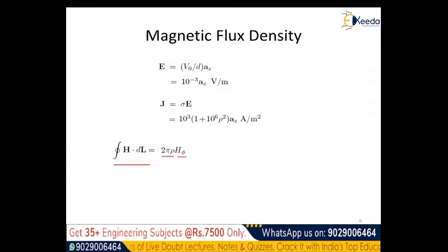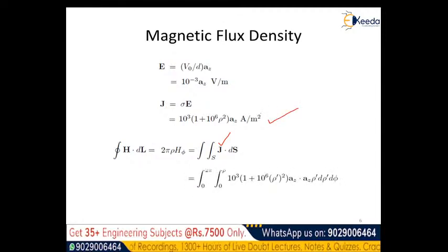So this we also can express in terms of the cross-sectional current density when integrated over the cross-sectional area. For the conductor, if you take the horizontal cross-section, it will also be of the circular shape, the exact same shape here. So here we denote it as the open surface integral j bar dot ds bar. Now to have the computation on the left hand side as represented, we can make the use of capital J, that we have to integrate along with the ds here. So here we substitute the capital J from the above step, and then we proceed here. So here we have the surface integral, that means the double integral here. The one dimension here we denote the integration 0 to 2 pi. Another dimension here we denote 0 to rho. So 0 to 2 pi is the entire range of the angle phi here.